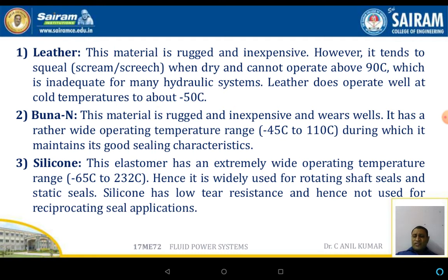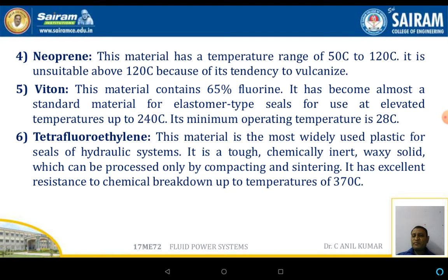Teflon has an operating temperature varying from minus 65 degrees centigrade to 232 degrees centigrade, above which the material will fail and there may be chances of melting, and it loses its properties at high temperature as well as at low temperature below minus 65 degrees centigrade.